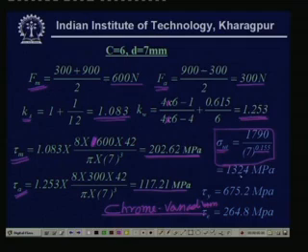That gives you a value of 1324. Again, if you go back to the relationship of sigma ultimate to sigma yield point, the yield point is sigma ultimate multiplied by 0.51 for chrome vanadium, and the endurance limit is sigma ultimate multiplied by 0.2. These are the two values from this calculation.